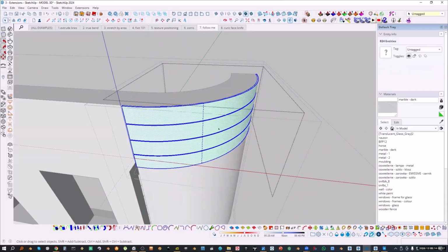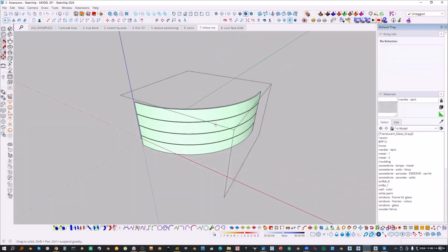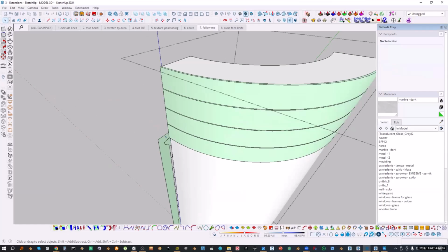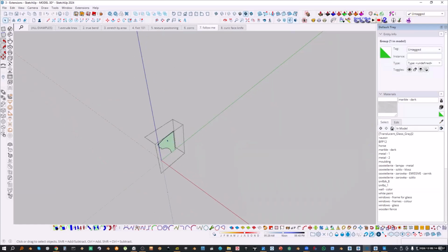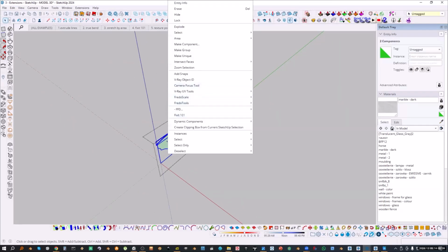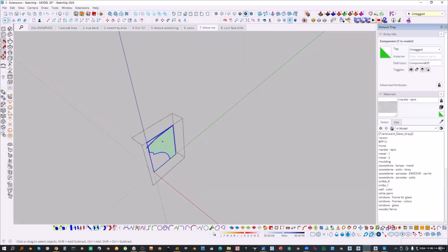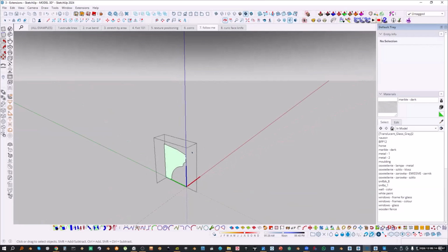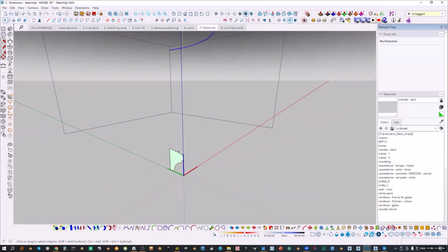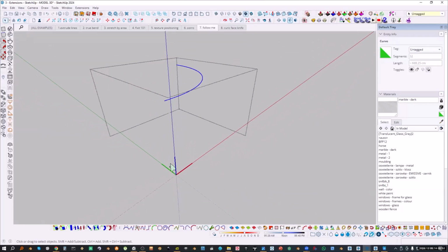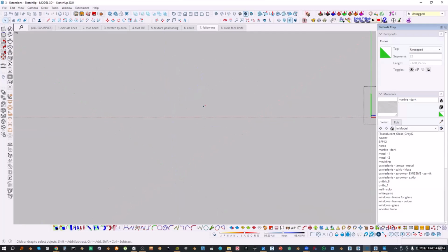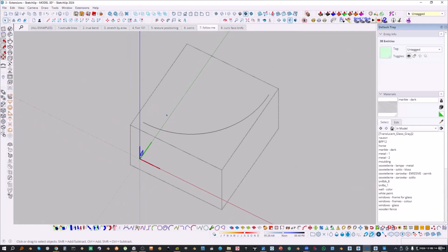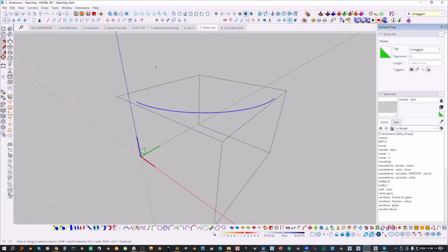I have it under the escape, which is tilde up. So now on to the next one. We still have the curved line in the memory, so we can utilize it. Let me just real quickly do it. So double click on the profile. So I have those profiles. I've drawn them earlier, and you don't really need to align that. It's actually already aligned when you look at it from the top. It is aligned here. So that's the only point of alignment that we require for Follow Me.